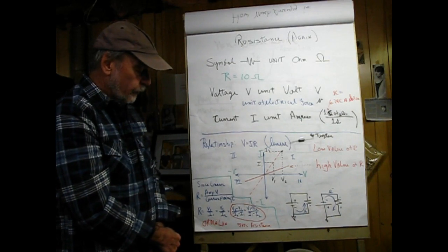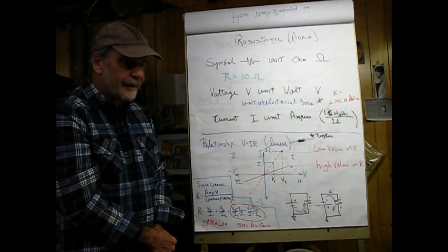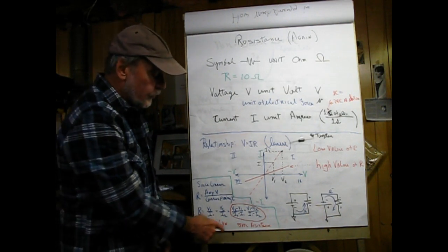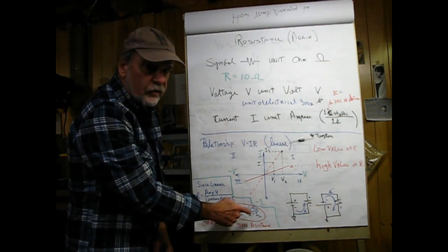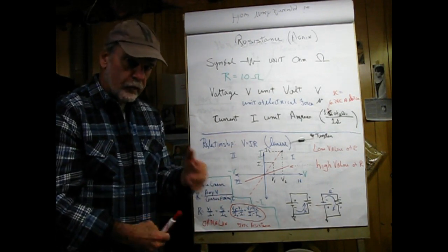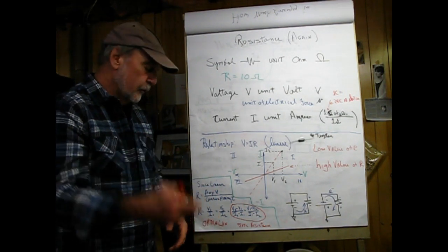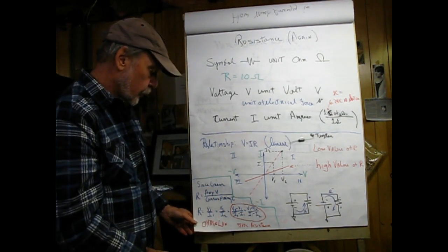If you pick two different values of voltage and their corresponding currents, and the ratios are not the same, Ohm's law does not apply. And this is in the static resistance sense. There's another type of application of Ohm's law which is called dynamic resistance. I'm not even going to discuss that here because that's a topic for later study.